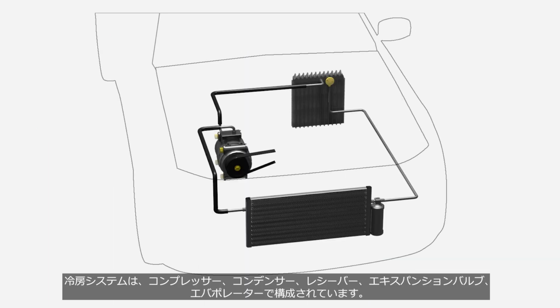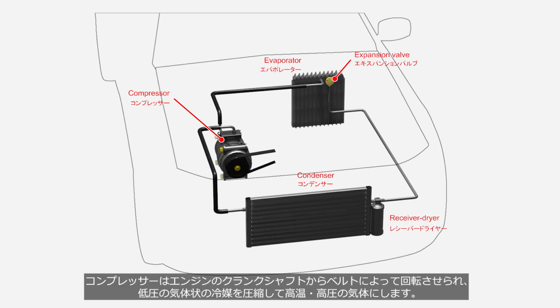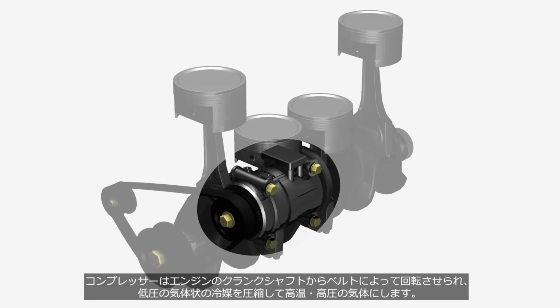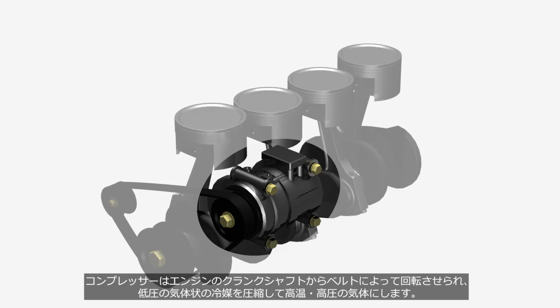The cooling system consists of a compressor, condenser, receiver dryer, expansion valve, and evaporator. The compressor is rotated by the engine crankshaft via belt, compressing low-pressure gaseous refrigerant into high-temperature and high-pressure gas.